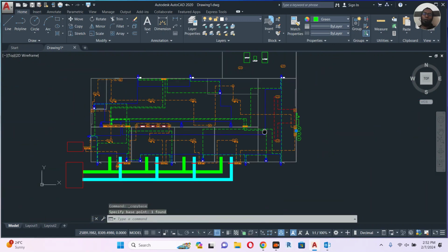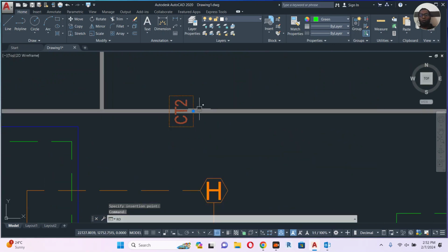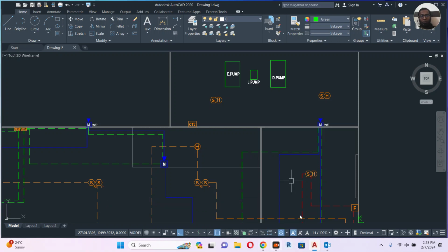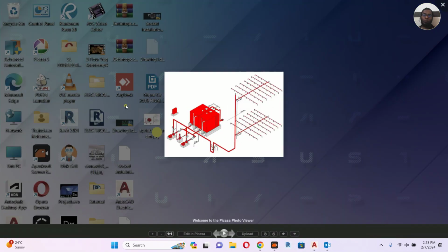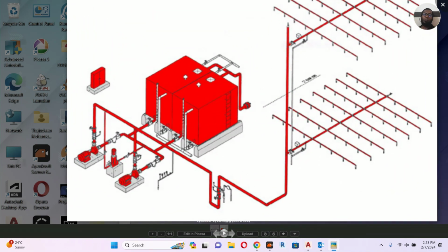As per my experience, almost more than 15 to 16 monitor modules will come here. So let's calculate ourselves. So let's go to the image. We will put one monitor module here, pump status, pump status, pump status. Let's imagine 3. Okay, we have gate valve here 2, 5. Here we have gate valve, and here also gate valve 3, meaning 8.